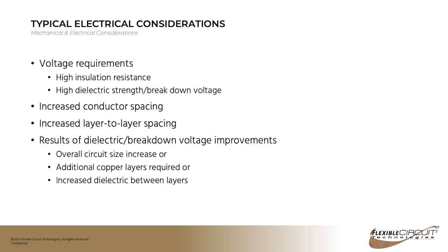And you can also increase your dielectric between layers. Again, fortunately, the polyimide films are really good. Typically 1 mil is more than enough, but when more is required, that's going to make the circuit even thicker.